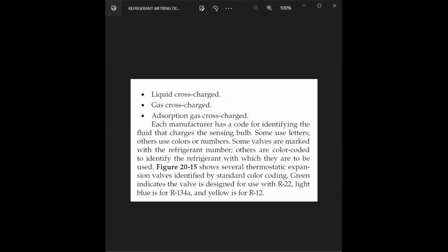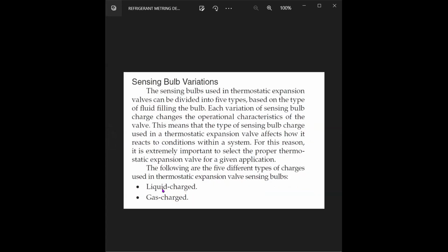That is the operating range. And for the liquid charge refrigerant, the operating range is basically minus 28.9 to plus 4.4. So the idea is, with gas charge, you are able to get your operational range basically much larger, minus 1.1 to 15.6 degrees Celsius. So that is the reason you would want to take this gas charge refrigerant.